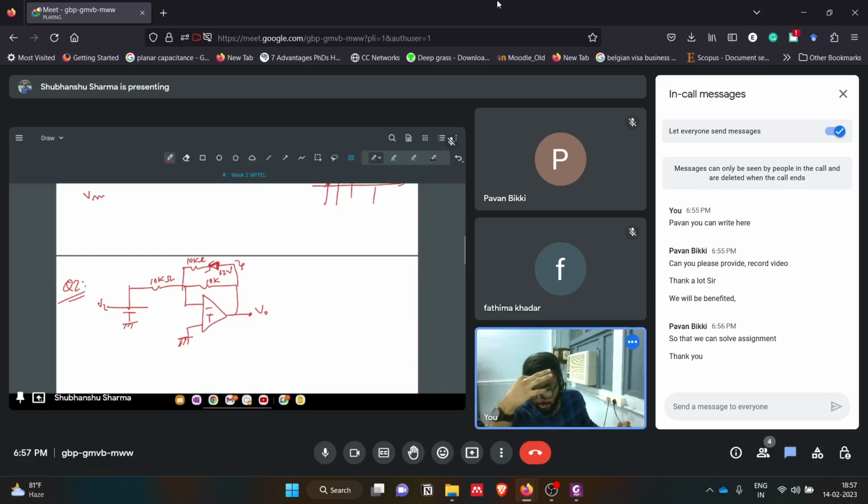That is simple. We have this V2, which was 1 volt. Here this is 0 volts, so this will be negative. Since we are giving a negative potential here, 1 volt, which is greater than the non-inverting terminal, what will happen? This will be negative. Anyway, this is an inverting configuration, so we get the negative output. Since this is negative, this output will be negative.